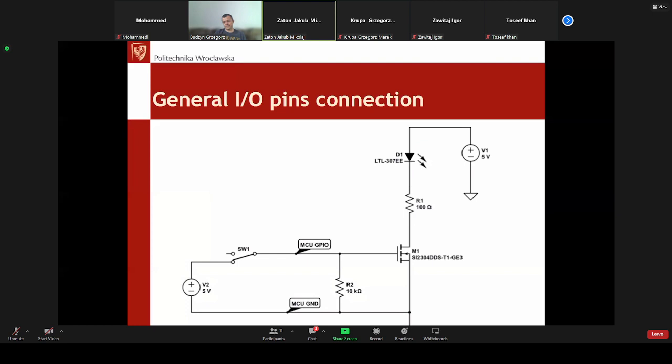For discharging the internal capacitor between the gate and the source. Very good. And if we discharge faster, what do we obtain with this? So faster discharging of the capacitor, what will it give us? Shorter fall time? Yeah, switch off will be faster.